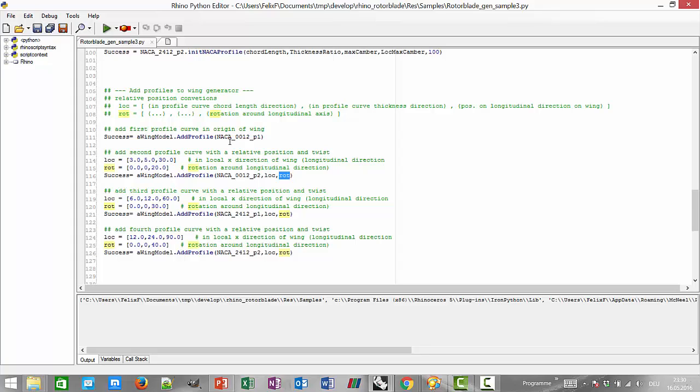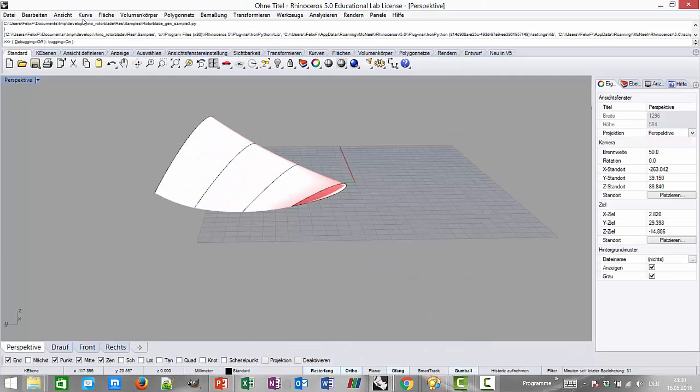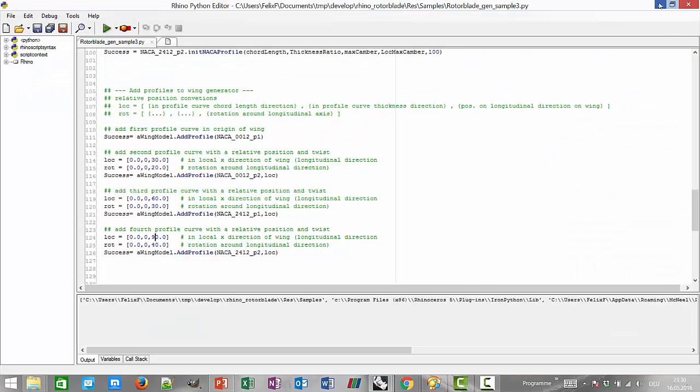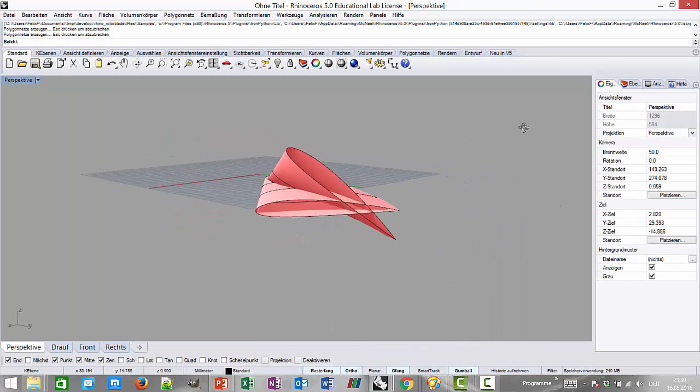So we could, for example, here say we have no local rotations, and actually these ones here should be 0. We don't want any kind of translations except the third one. This is the important one in the longitudinal direction of the wing, but the other two, which you saw on the slides, something like in-plane and out-of-plane translations, should be 0. And if I didn't make a mistake now, no I did not, you will see here that this model